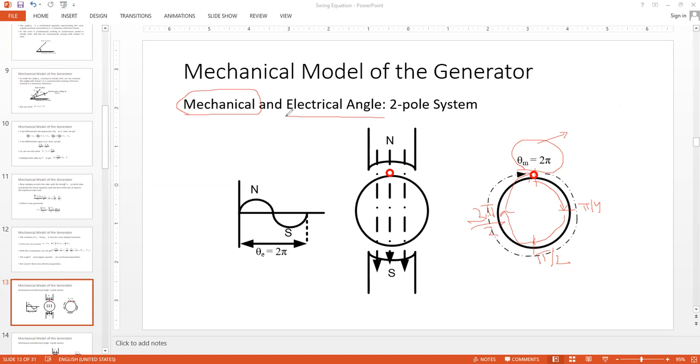On the other hand, the electrical angle is purely dependent on them. Electrical measurement means we are trying to measure the position or location of an object with respect to some magnetic flux lines. So the electrical angle is absolutely dependent on magnetic flux direction. Mechanical measurement has nothing to do with magnetic flux direction, magnetic poles or flux lines. So this is the summary. Now let's apply this information on the figures over here.